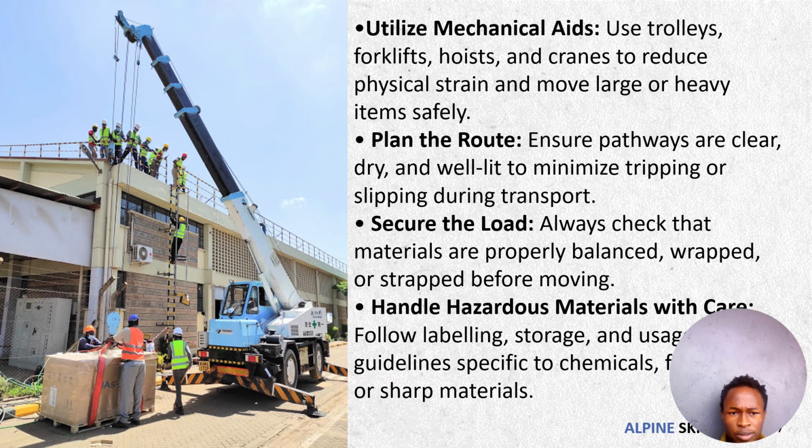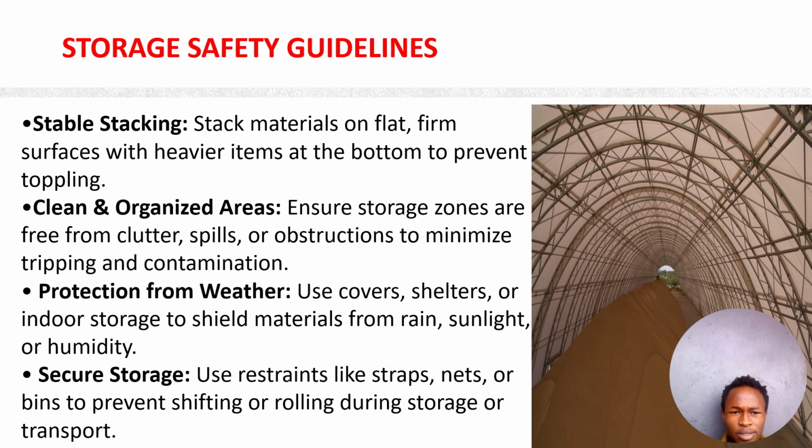As we proceed, another subtopic is storage safety guidelines for materials. Number one, we have stable stacking, which is stacking materials on flat, firm surfaces with heavy items at the bottom to prevent toppling. Clean and organized areas ensure storage zones are free from clutter, spills, or obstruction to minimize tripping and contamination. And then you have protection from the weather. Use covers, shelters, or indoor storage to shield materials from rain, sunlight, and humidity. In the presentation, you can see a cover that has been used to protect sand from the weather.